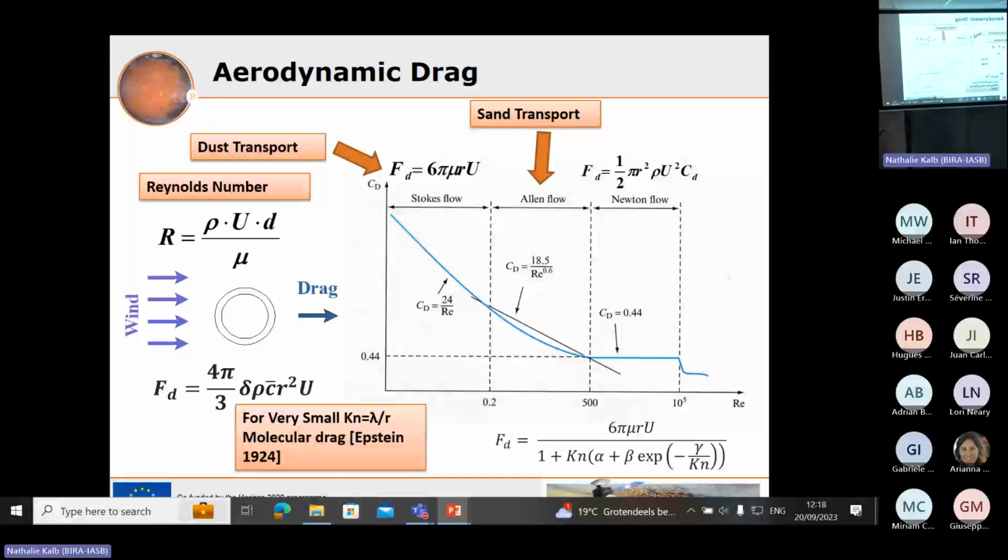He made a really good equation which works very well down in the molecular regime, where your drag is essentially single molecular impacts doing the drag. And it's characterized by when this Knudsen number becomes around 1 or bigger than 1. It is the scattering length or mean free path divided by the particle radius.